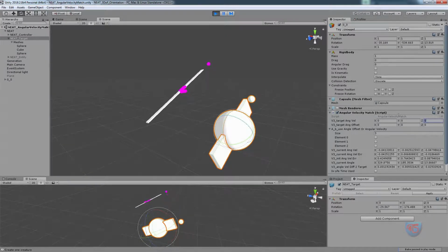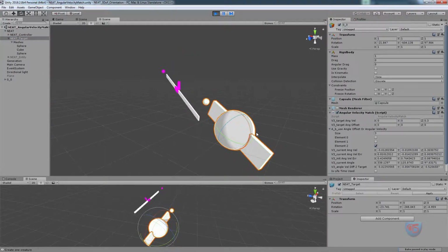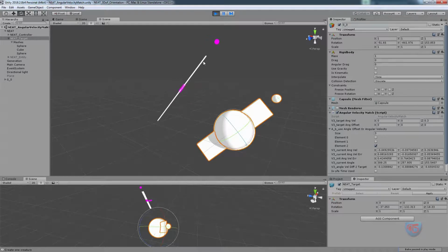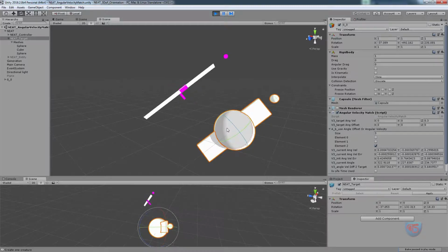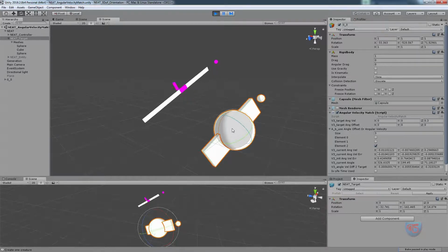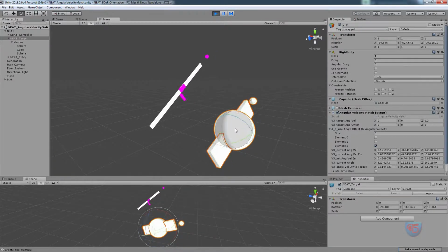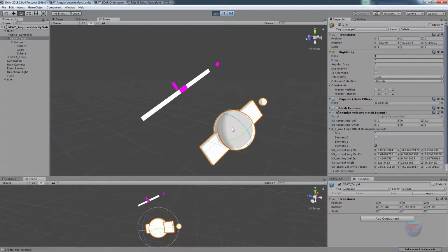But if I spin along my own axis, let's say axis Z, which in this case is the forward axis, and I try to use the equivalent thrusters, of course I cannot fire the same thruster. Now I fire at a given time the thrusters on the left side, at some point on the right side, and on top, on the bottom. Of course it's rotated 180 degrees, everything is opposite. So I need to adjust those. That's why I get a bit of wobble.